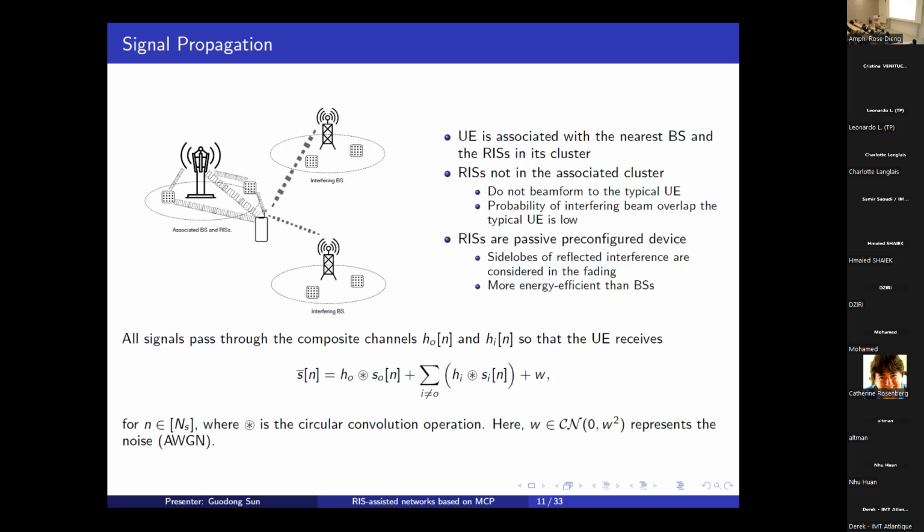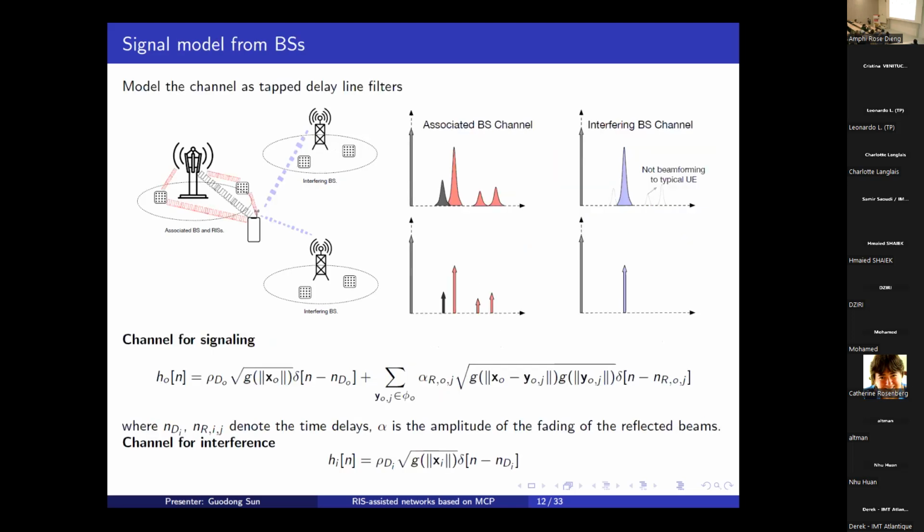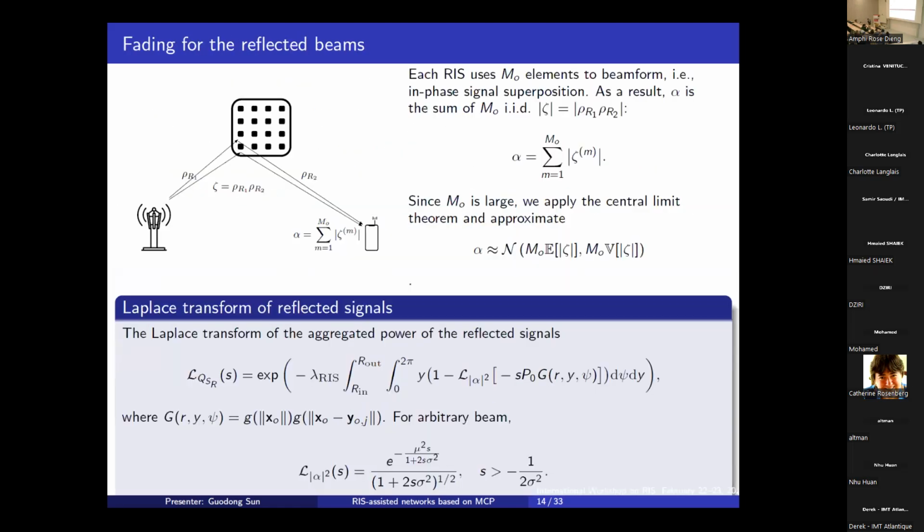Yeah, but do you take into account in the propagation channel models other reflectors than the RIS? Yes. So it means a variation of the channel, right? Like other scatterers. It's captured in here, the fading of the link between base station and RIS, and the fading between RIS and user. So rho denotes the small scale fading, because of small multipaths around each scatterer.